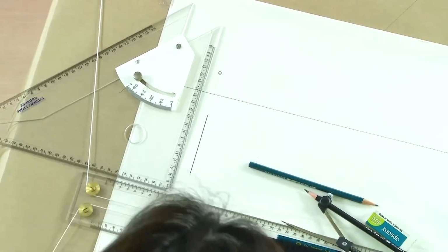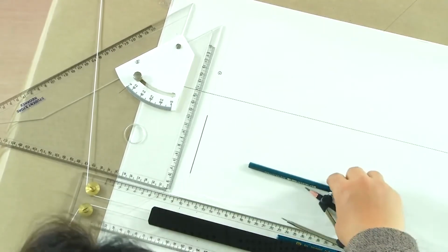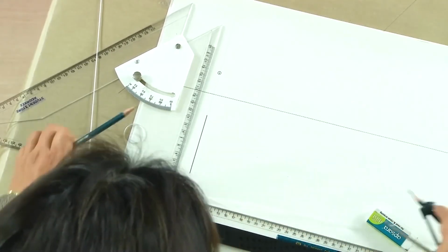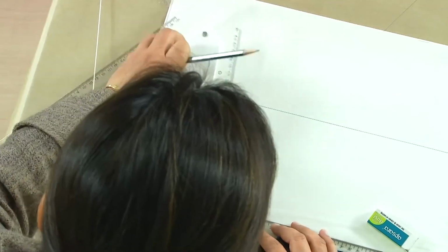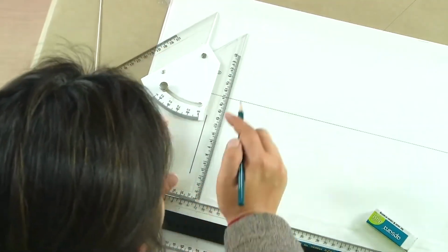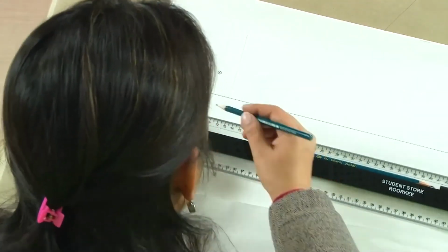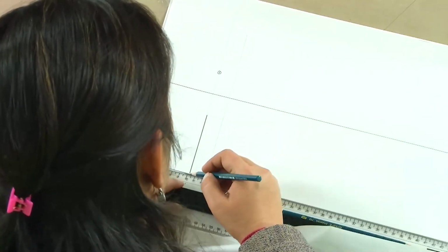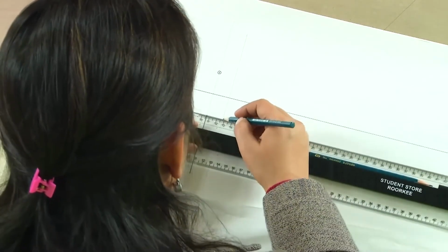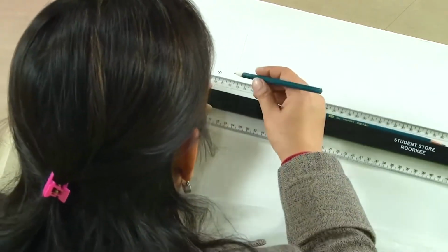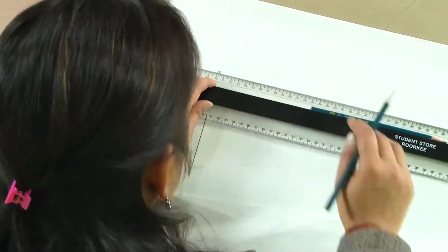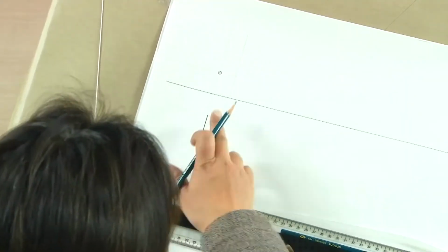If we have to draw the side elevation now, let us draw the side elevation on a side plane. Say the side plane is starting slightly away from this. So, we first take the projections up to the side plane.